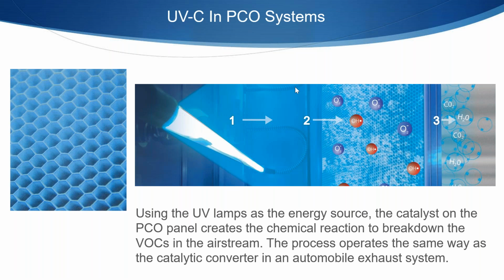One thing I have seen through the last year is a shift where there were companies that were providing VOC mitigation and odor mitigation before the pandemic, and then when the pandemic hit, they really jumped in on, hey, let's look at pathogen control a little bit more, let's look at airstream disinfection a little bit more. And when this happened, it kind of confused some people. So if you're designing a system for airstream disinfection, you don't need photocatalytic oxidation. The active part of disinfection is the lamp system. So if someone is trying to convince you that this whole system is necessary to provide airstream disinfection, you might want to look into that a little bit.